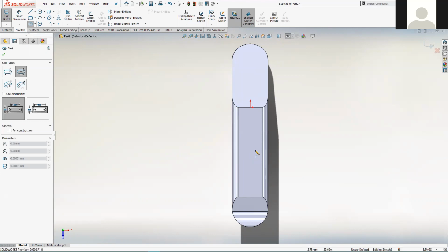And then if you hover directly below the origin there, so we switched our planes off in that other feature that we were doing. And at this point, it might be useful to bring them back again. So I'm just going to go up there and click on the eye at the top to bring the planes back again. There they are. And then I'm going to click roughly in the vertical center of this face, so somewhere around there will do.